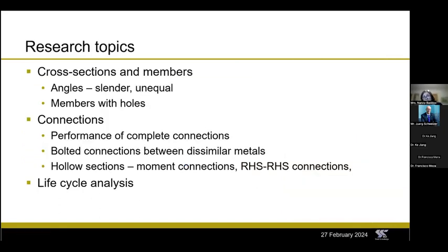So my closing slide on research, just a few suggestions. We're still needing comprehensive design rules on stainless steel angles, which is sort of funny because when I started working in the field of stainless steel more than 30 years ago, it was with masonry support angles that I started, and yet we're still needing comprehensive rules on the behavior of slender cross-section angles and unequal-legged stainless steel angles. And there's work underway in the States, at Imperial College London, possibly elsewhere too.